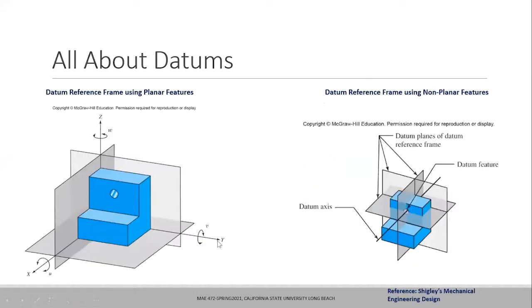So as I said, the datums, which are basically the theoretical planes, are nothing but the surfaces of the feature simulator, which is a surface plate or maybe a machine tool bed or some other precisely machined or flat objects. So that will be used to construct the reference planes, and the intersection of these reference planes will define the origin of the measurement.